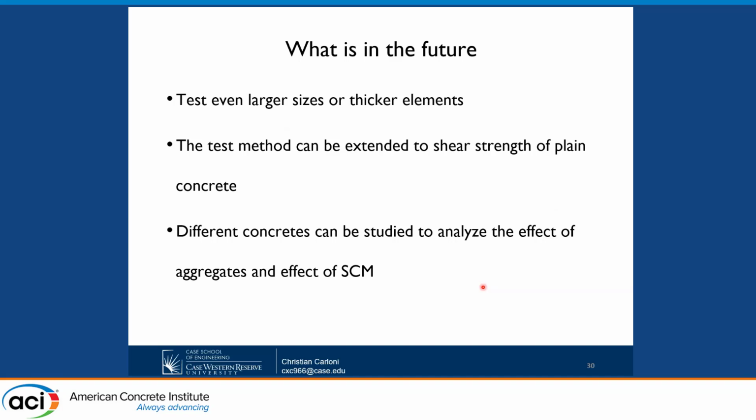If you use fly ash, this is going to be even worse, because we did some tests I'm not showing today. The fly ash, the unreacted fly ash, is a very, very easy path for the propagation, because fly ash is spherical, it's a perfect sphere, and your crack will not go around it as it does with aggregates, it will go through the sphere very easily. So whenever you use supplementary cementitious materials, this size effect can be even more pronounced. So I think this is really where we're looking to understand more. And once we know this, then modeling is very simple, I think.